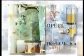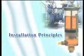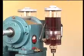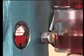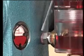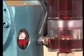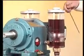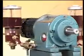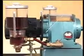Now let's demonstrate the installation of TOM and show its distinctive functions. Installation principles. Many bearing housings have a hole horizontally parallel to the standard oil level. In this case, we install TOM at the hole through a steel tube with thread at either end. This is the most ideal installation mode. In case of no such hole available, we can install TOM through a T-type tube at the oil drainage hole on the bearing housing.